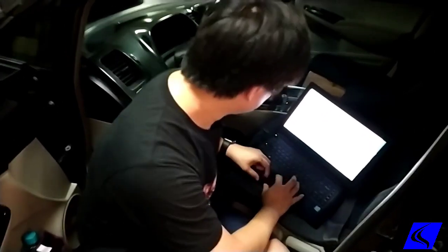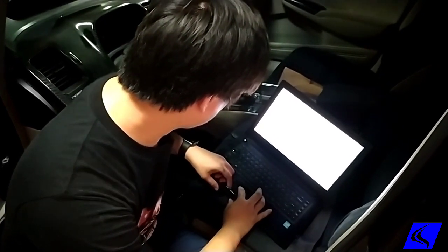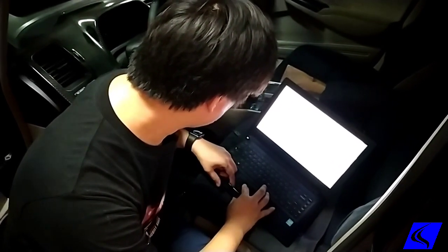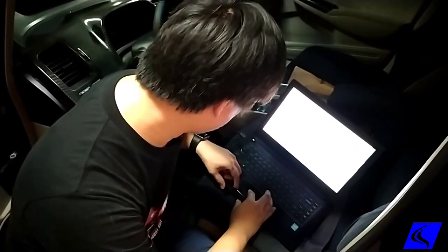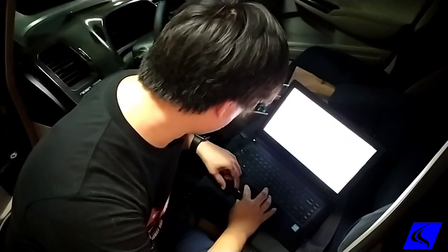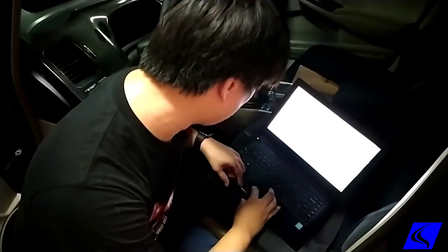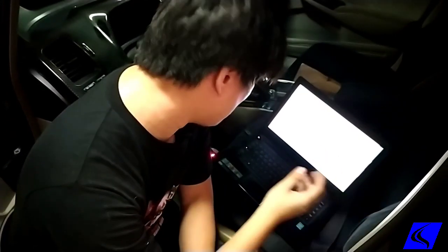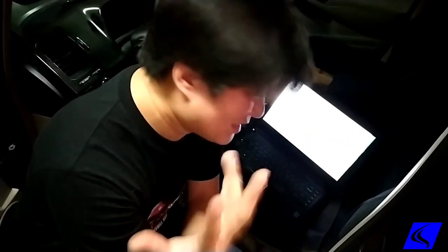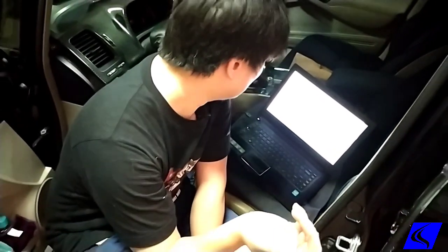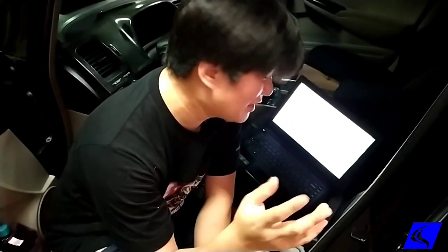There you go. So these are the things that we're able to alter. Fueling, timing, rev limits. This is also timing here, then throttle control is here. We can actually alter the VTEC point also, but there's not much point in doing that. Making the VTEC lower does not give you any more power on these cars because it's not the same VTEC as you find in the old SIRs and B series engines. No. The new i-VTECs are nowhere like that. It's a totally different world already.